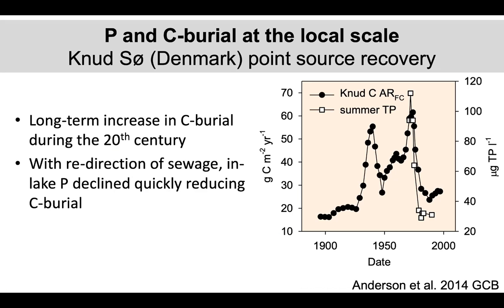Adam, I'd assume that you would expect that tracking to be even closer if you were looking at dissolved phosphorus rather than total phosphorus, so bioavailable phosphorus. Yeah, if we were looking at SRP coming in at the pipe, I'm sure that would be an even closer correlation. SRP is a bit tricky in epilimnetic water because most freshwater lakes are phosphorus limited, so it's basically drawn down as soon as it's available. And so almost all the phosphorus in epilimnetic water is in algal biomass.